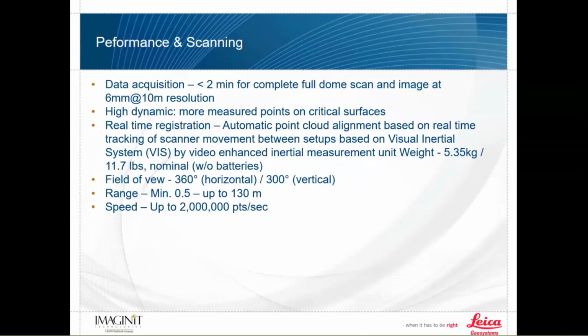But when I get inside, it gets a lot better, mainly because those 5 cameras are attaching themselves and assigning XYZ coordinates on all of our sharp corners. That's how it's tracking us. We get down to quarter inch to half inch accuracy. When I put all this together in the iPad, I'm now running much, much tighter, and my registration is so much easier. It does have a minimum range and a max range. Minimum range is about 1/2 meter, or 18 inches or so, and the max is about 300 some odd feet.